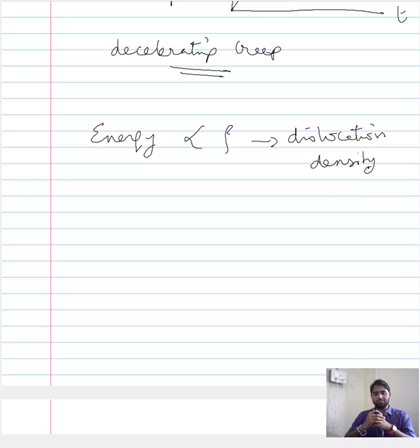Now in the general case, we have no ways of decreasing this energy, and we continue imposing the mechanical condition to arrive at a definite state or to arrive at the desired properties. However, if you want to decrease this dislocation density, thereby decrease the overall energy of the system, what would you do? Supposing you have imposed a sufficient amount of plastic deformation to a material such that the dislocation density has sufficiently increased and it is too much for your application, then what would you do?